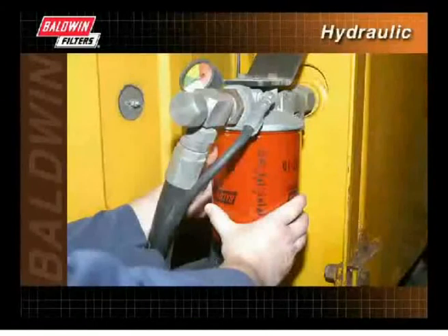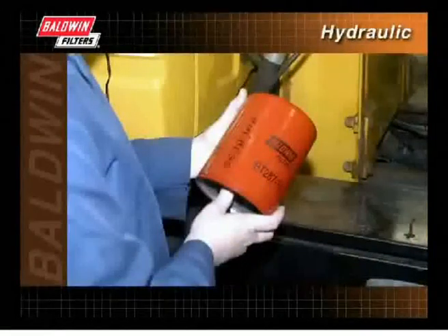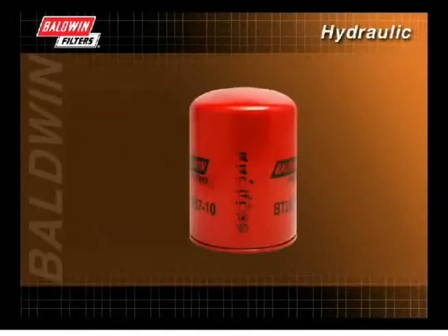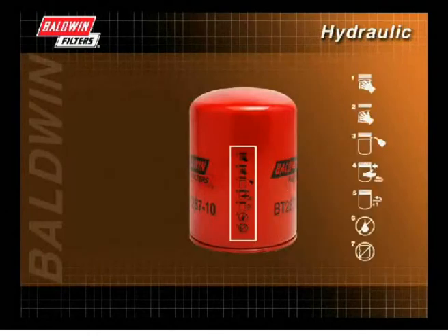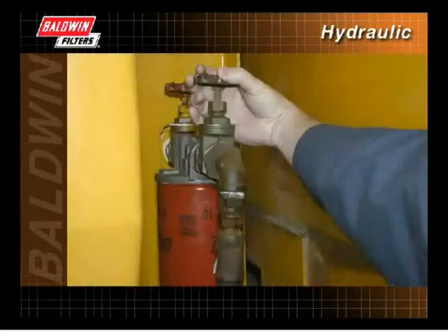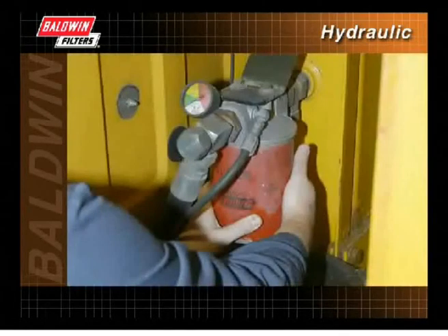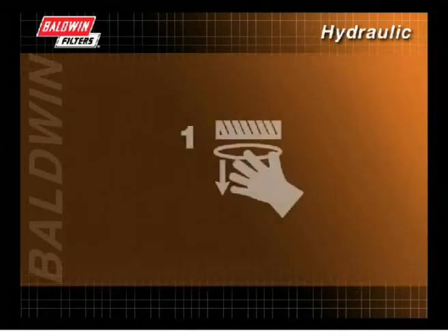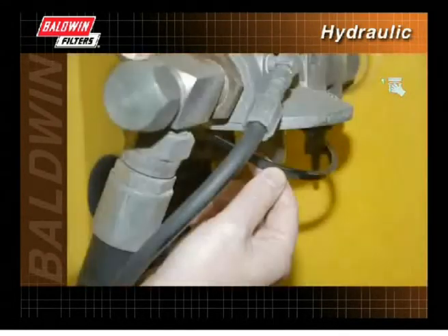To ensure normal hydraulic filter service life and prevent fluid leakage or possible internal engine damage, it is important that correct installation procedures are followed. Most spin-on hydraulic filters include pictograms on the filters themselves, showing the proper installation procedures. When servicing, first close the shutoff valve to prevent spillage. Unscrew and remove the old filter, making sure the old gasket is also removed.